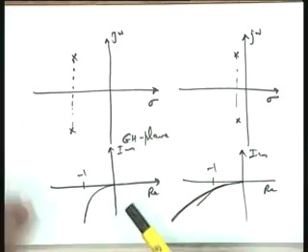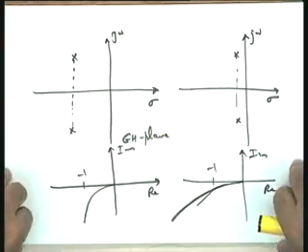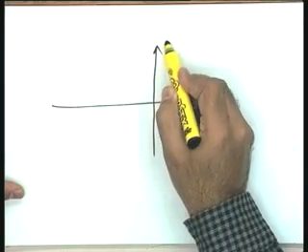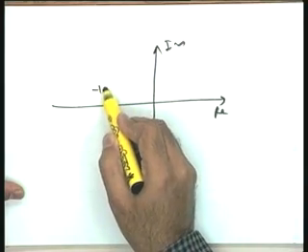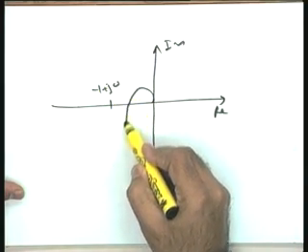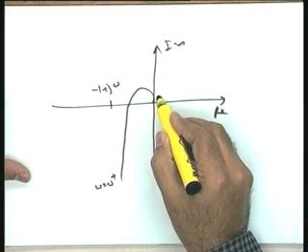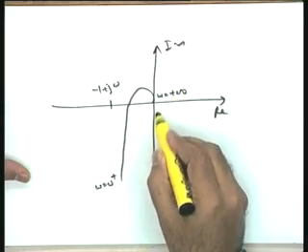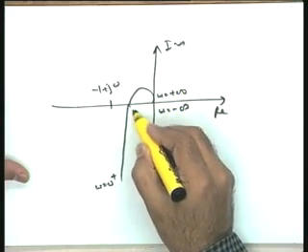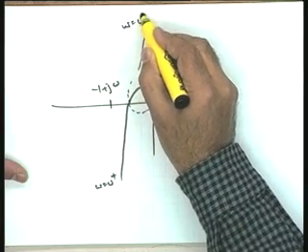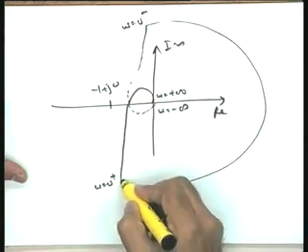Now, here I can say that the polar plot portion matters most. If I give you a complete Nyquist plot, you will realize that primarily we are interested in the polar plot. This is the real part, this is the imaginary part, this is -1 plus j0, a typical system. This is omega equal to 0 plus, this is omega equal to plus infinity, then omega equal to minus infinity going to omega equal to 0 minus, and this is getting closed.